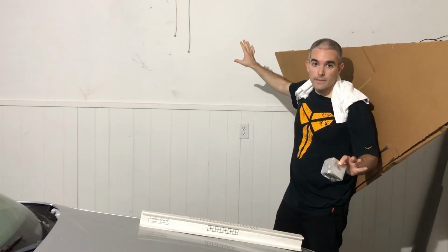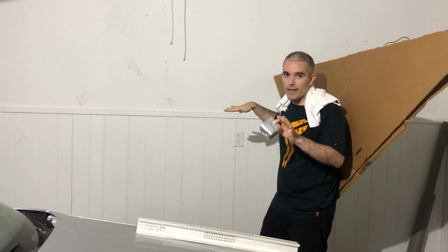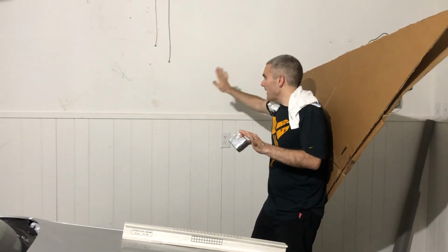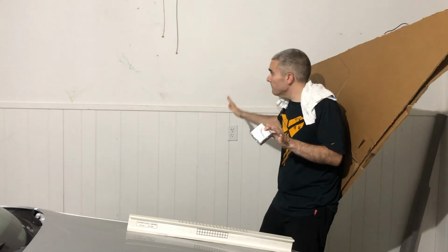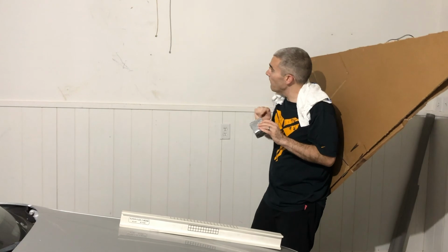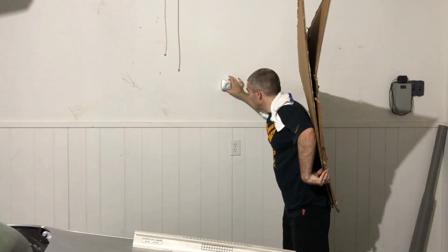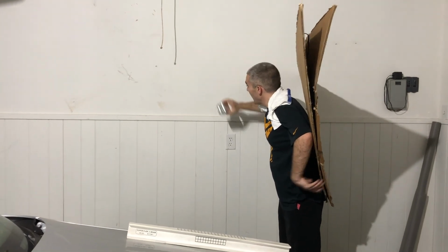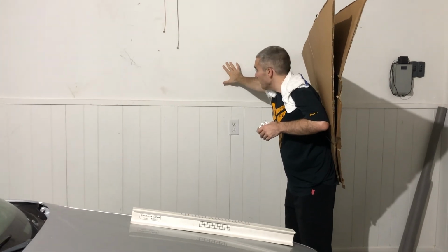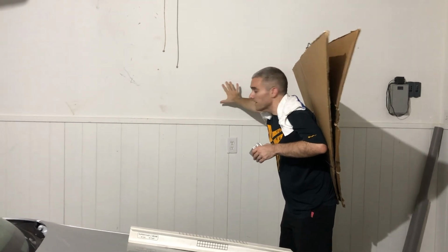You can see the wall is big. It has forces acting on it, even if we had some earthquake or lateral wind forces or something, a big storm's coming. It would have shear stresses, and it has forces up and down and everything, but everything's happening in one XY plane. Does that make sense? I think we could come in here and pull our block out, and we would see that on the surface here, there's no stress on the surface. The only way there would be stress on the surface is if I was actually physically pushing there, or there was something pressing or some pressure there.